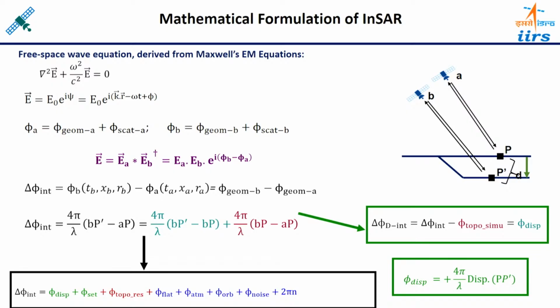It means decorrelation noise is there for a given set of images, whatever you have chosen. Now you cannot further minimize the baselines. Whatever baseline has been chosen, that baseline will remain, and the decorrelation corresponding to that baseline will remain in the signals. So you can say that much noise is there in the calculations. That is called the decorrelation noise.